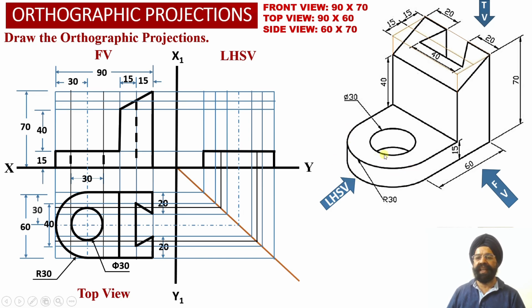And another thing we also know, corresponding to these two endpoints of the diameter, two vertical edges are available, which are not visible to the observer from the left hand side view over here. So now the hidden line projections we are going to obtain into the horizontal web in the left hand side view projections over here.